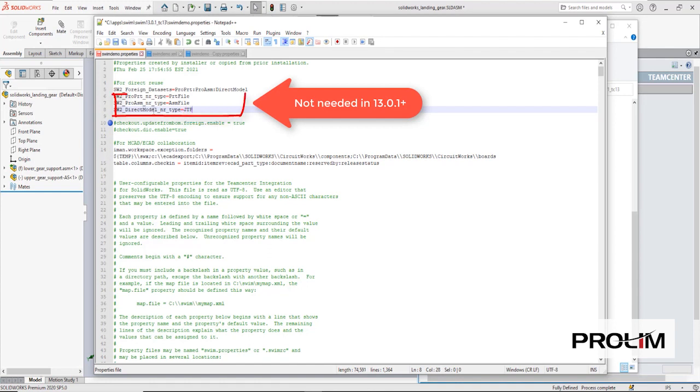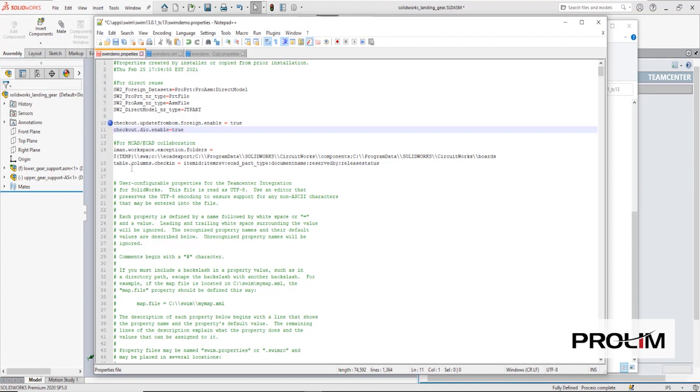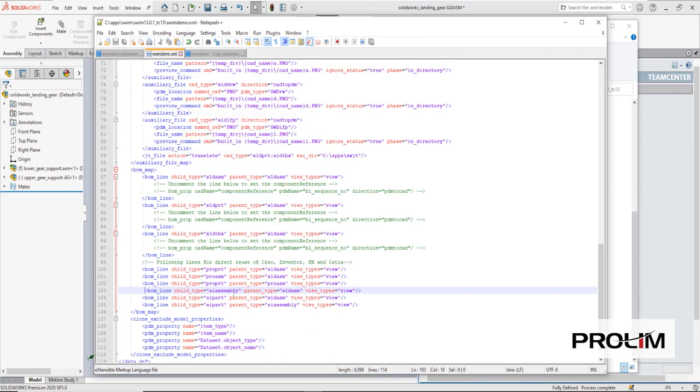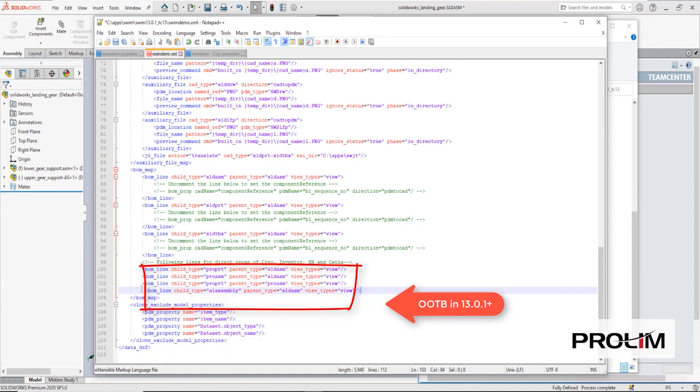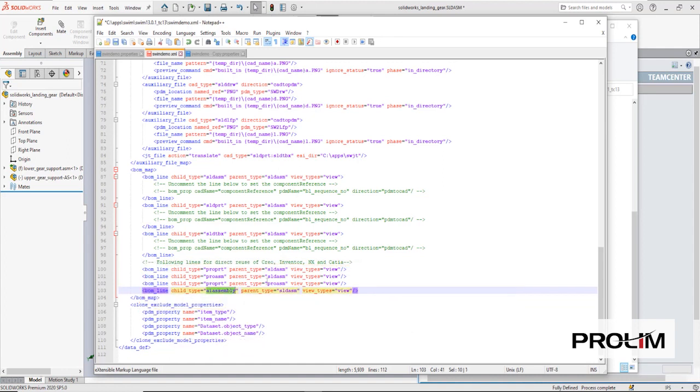In addition to the general settings in swim.properties, 2 additional preferences are needed. The first allows the integration to build transient SOLIDWORKS parent assemblies using the JT, or other, parts. This setting is also needed for hybrid reuse, as we will see a bit later. The second preference is specific to JT and is needed due to certain implementation details.